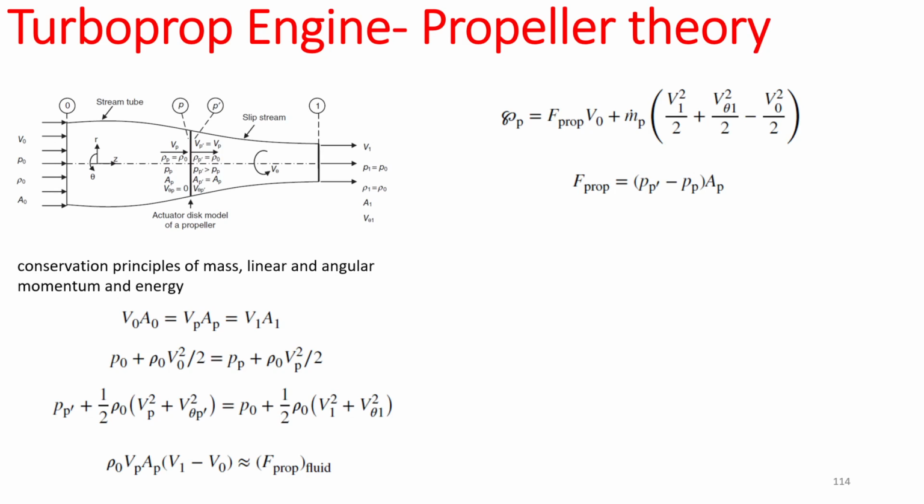When we say the shaft power here, we are talking about the shaft power that is provided by the turbine. So here, we are actually calculating the power that is necessary to rotate this propeller, right? It is the thrust power provided plus the momentum jump, right? And in the momentum jump analysis, we are also including the swirl velocity as well, right?